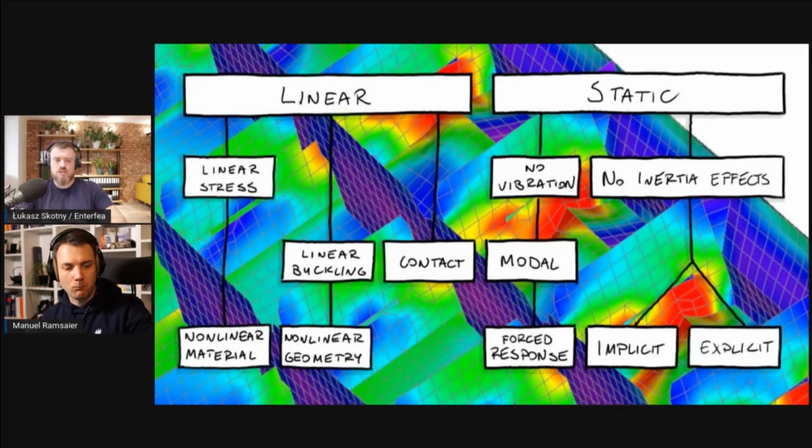And then, of course, if you want to design something with linear static, you would expect that there is some value of stress that you are willing to accept, and then the higher values are not acceptable. And this limit can be a lot of different things depending on the industry, material, or whatnot. But the idea is the same. As soon as I get this much stress, the thing breaks. The problem is that because of the limitations of linear FEA, or maybe even FEA in general, you will reach this value in a very small area very, very quickly.